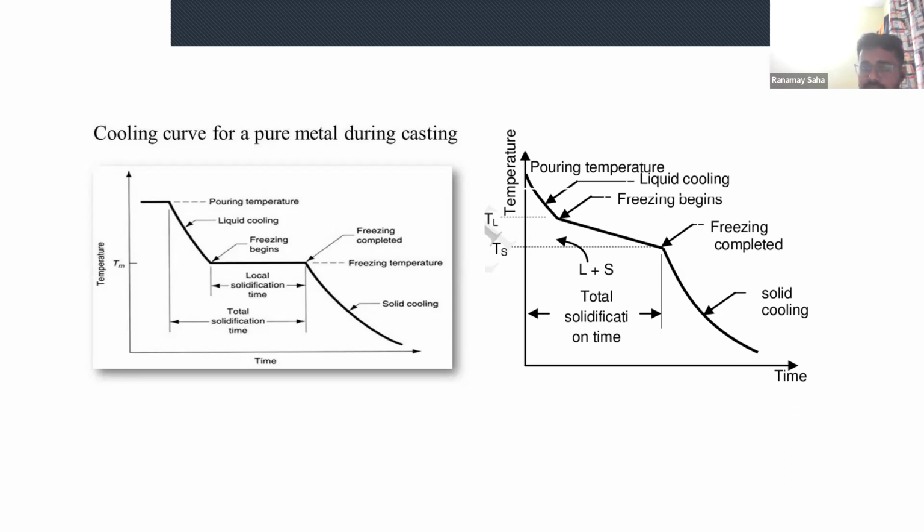As a result, there is a density variation, because the grain structure is different. This ultimately leads to defects and a weak structure of the product when it is realized out of that material. So in the case of alloys, you have to take care of these things.